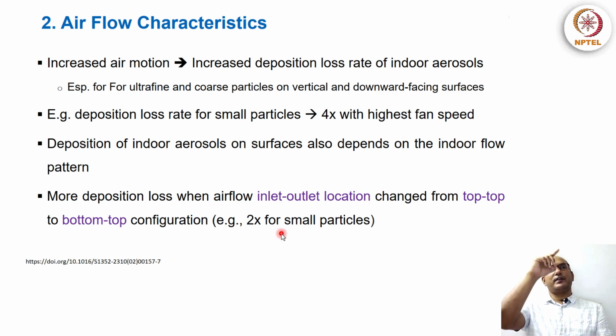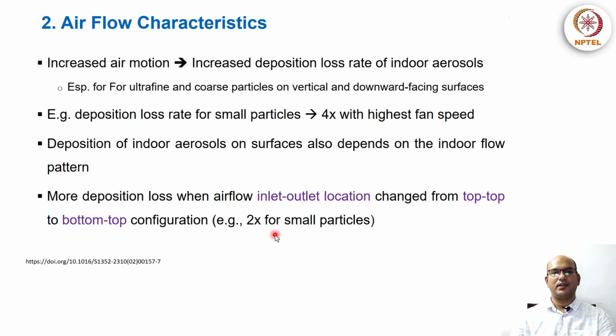If inlet is top and outlet is top, this is our airflow, perhaps with less chance of impaction of air with the wall, but in the bottom-top configuration, the air is going and maybe there is more chance of colliding with the surface. So therefore more chance of the smaller particles to stick to the surface. So in addition to the airflow speed, the airflow pattern also becomes important.